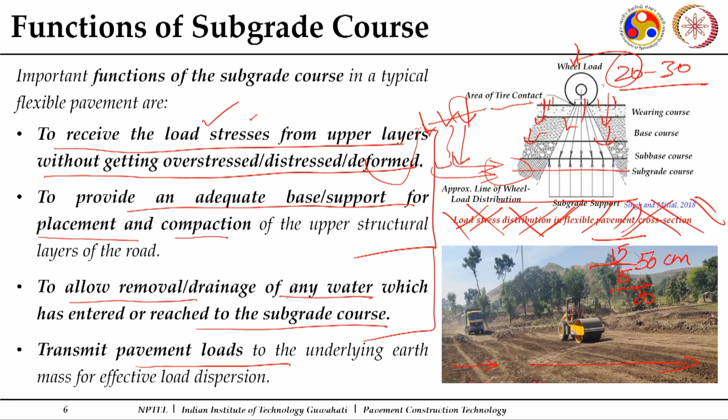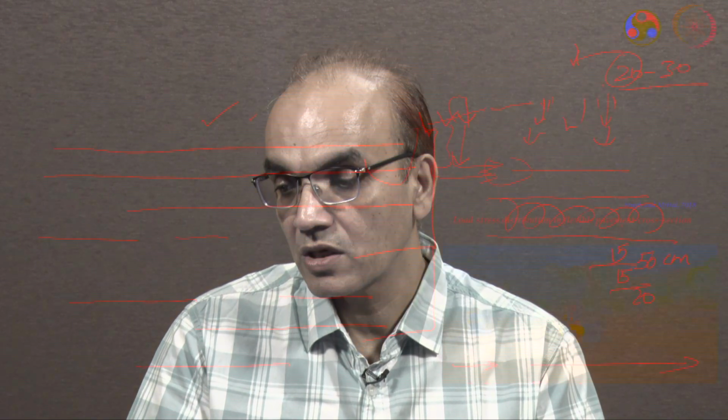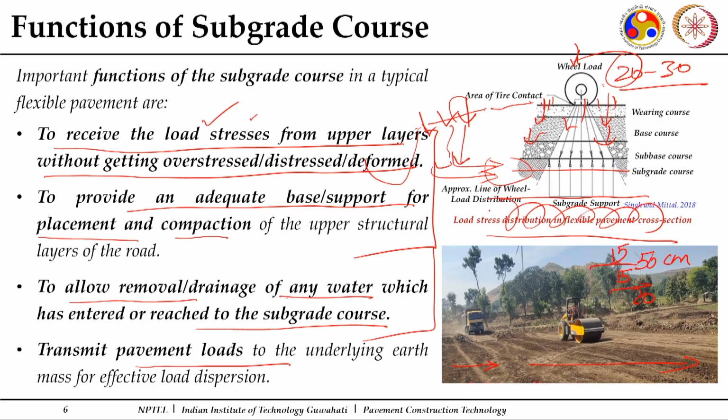Yesterday in the last lecture we discussed that you can have embankments of height more than 6 meters, and there is a particular standard which is to be referred for the construction of embankments of height 6 meters and more. So, if there is an embankment also, whatever loads finally come to the embankment, it should be within the allowable capacity or bearing capacity or load carrying capacity of the embankment.